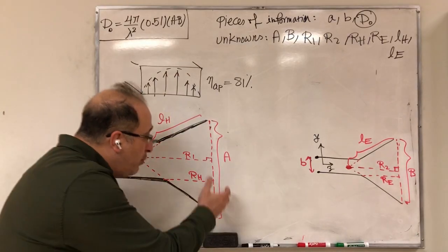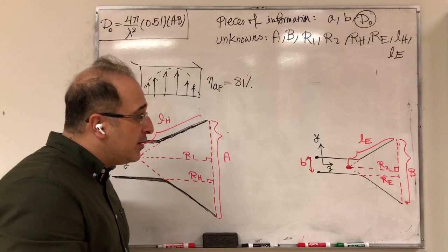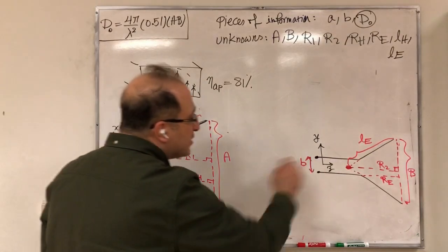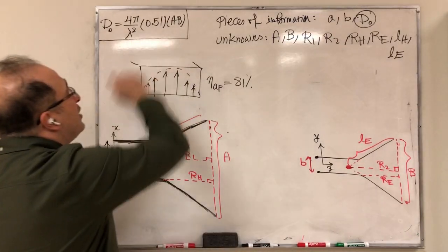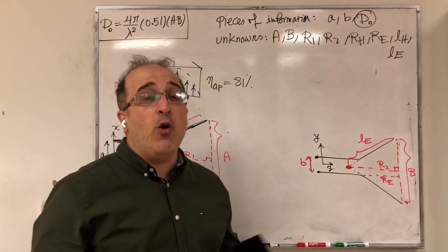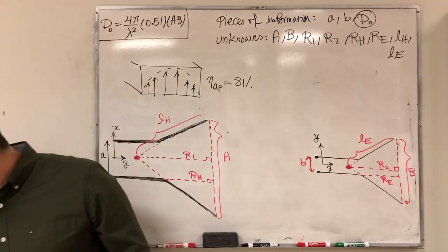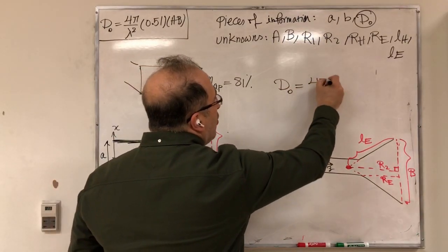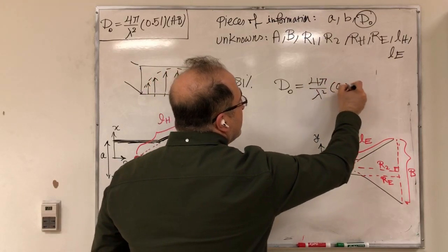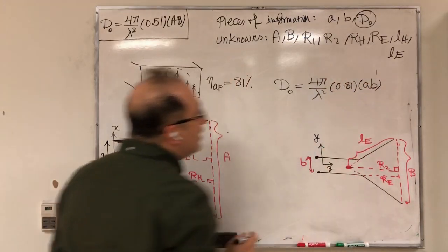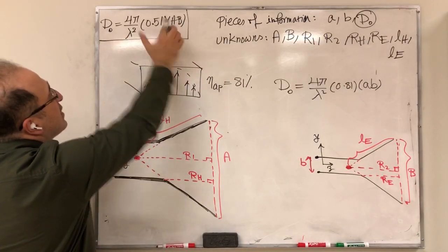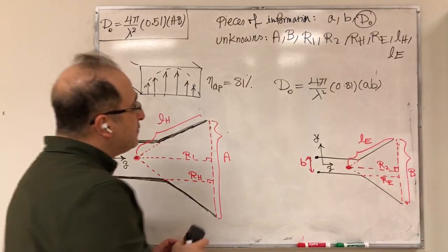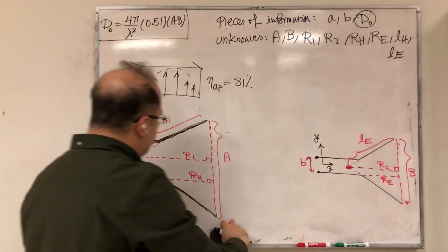So remember, you make your physical aperture bigger, because capital A times B definitely is greater than a small a times a small b. But the price that you pay would be on the aperture efficiency here. But overall, the expectation is you're going to still gain. For example, if you compare directivity of open-ended waveguide, which is 81% times a small ab, you expect that eventually this is going to be bigger than this. Therefore, you're going to get higher directivity. So that's something to keep in mind.